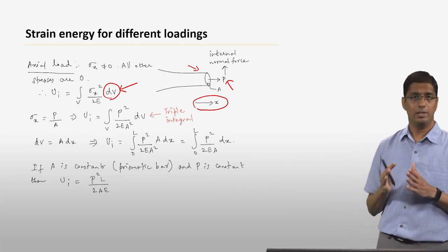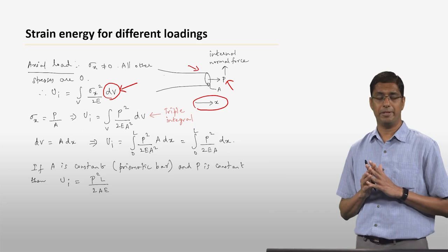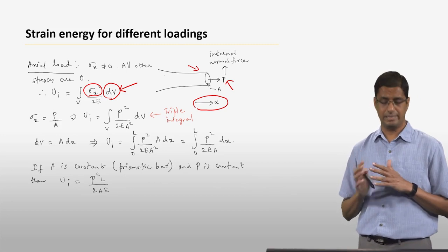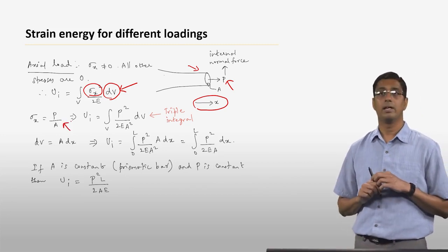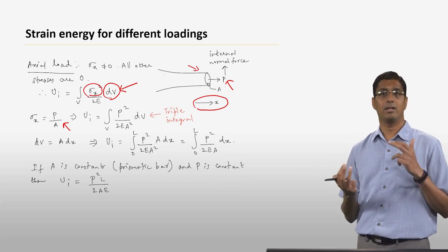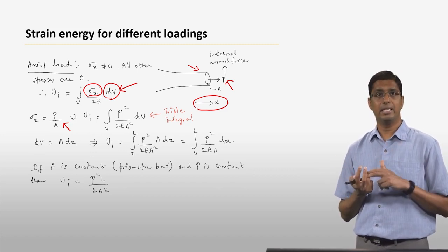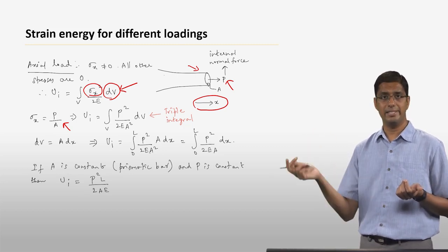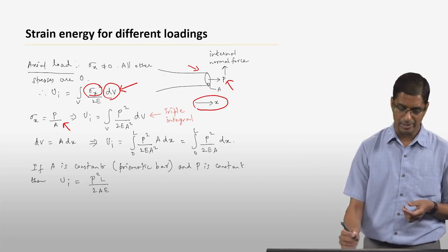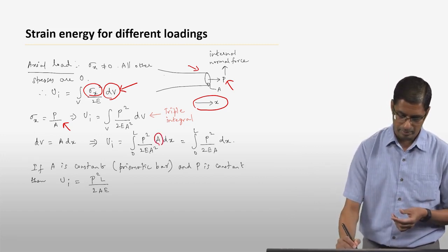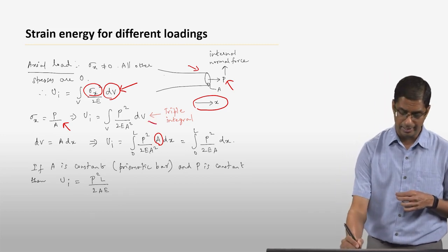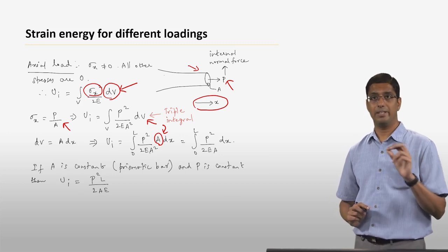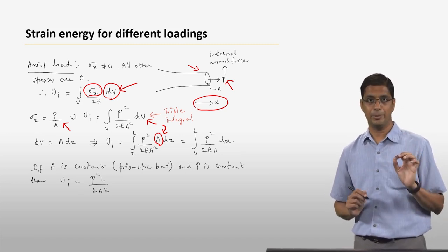But now, for this axial loading case, it becomes a little bit simplified because your sigma x is uniform across the entire cross section, which is nothing but P over A, right? So when you integrate along the y direction and the z direction, the value of sigma x is not going to change. So essentially the integral over dy and dz is nothing but the area of the cross section. So this triple integral here essentially becomes a one-dimensional integral where the integration is done over just dx. That's something that I want you to really understand.